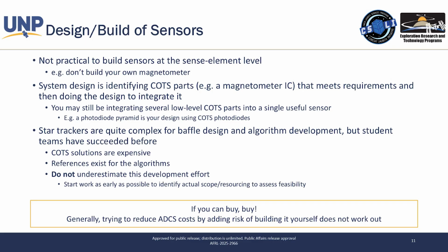If I had a really strict power budget, would it be very important to have a fine sun sensor that's well calibrated? Yeah, I guess you could use it that way. So, right, solar panels roughly fall off like a cosine wave. When you're pointed straight at the sun, so your normal vector is parallel with the vector of the sun, that's essentially 100% generation, right?